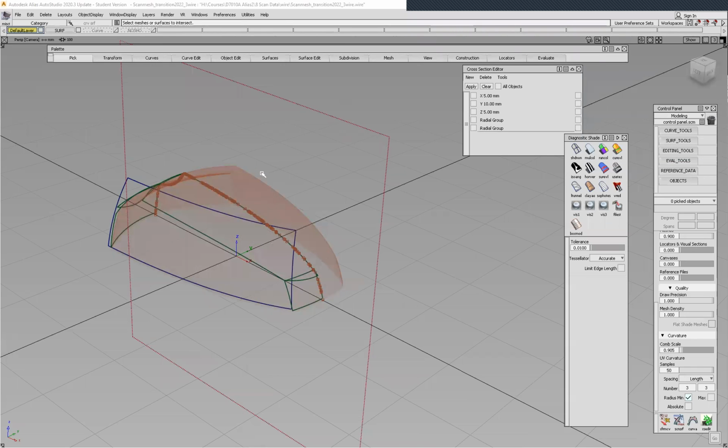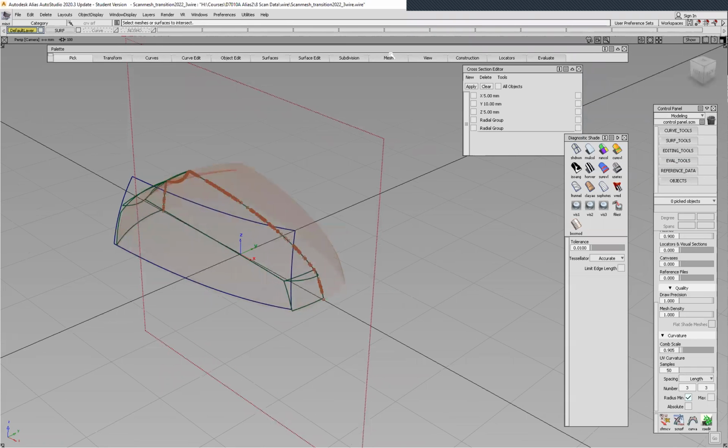Okay, so we cut the mesh by using mesh partitioning, mesh cut, like so. We pick the mesh and go select the curve on the mesh, which is right there. We go cut. There are two components. Select components as subset. It's kind of like trimming a surface. So I click this part here and I click keep.